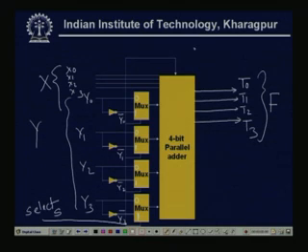So, what we can tell is that this is my C in and here is a C out. So, using 4 multiplexers with one select line, that means 2 to 1 muxes, a 4-bit parallel adder as well as a 4-bit subtractor can be designed in this way.